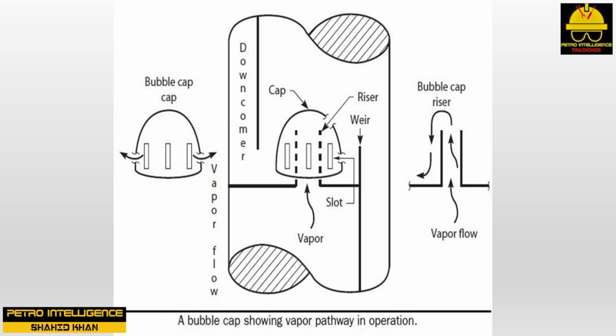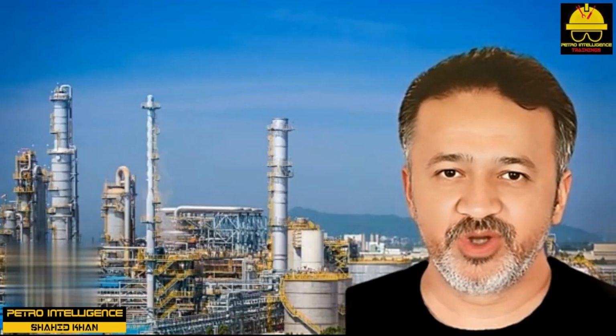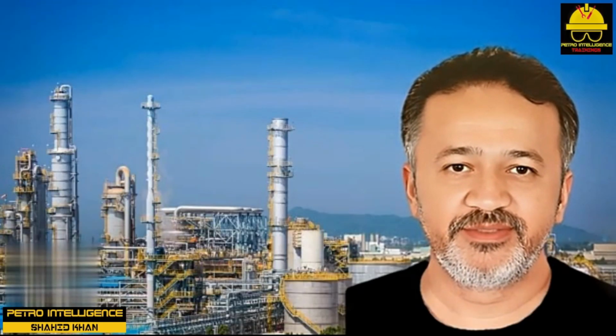Bubble cap trays. The major advantage of a bubble cap tray is that the tray deck is leak-proof. As shown in this picture, the riser inside the cap is above the top of the outlet weir. This creates a mechanical seal on the tray deck, which prevents liquid weeping, regardless of the vapor flow. Bubble cap trays may be operated over a far wider range of vapor flows, without loss of tray efficiency. In this picture you can see a bubble cap showing vapor pathway in operation.